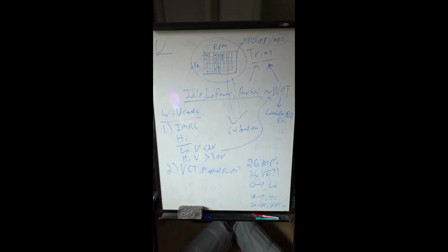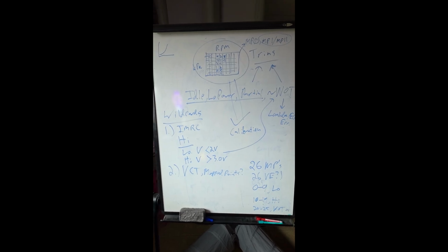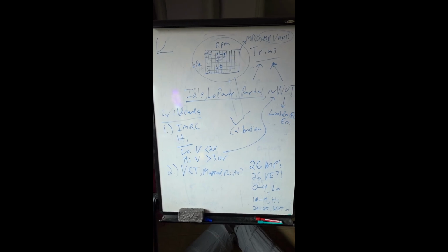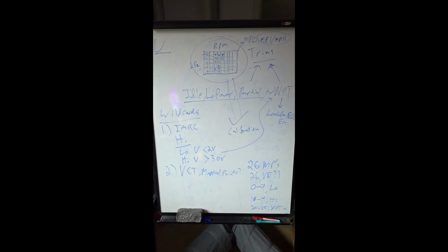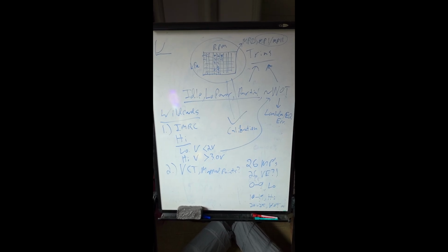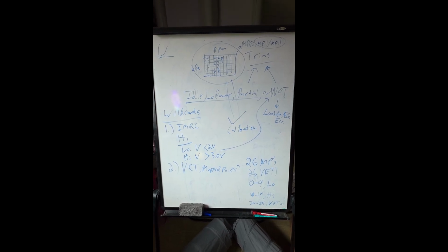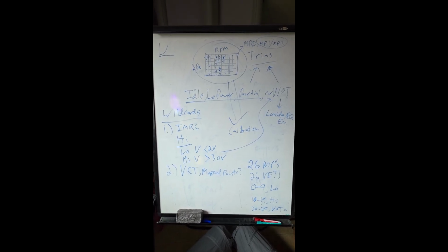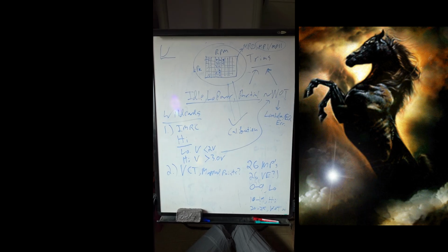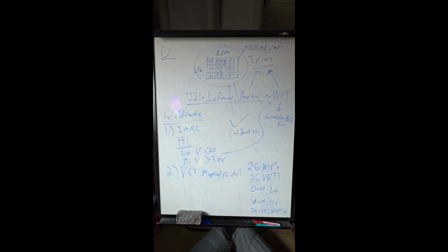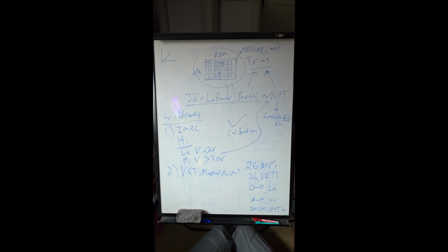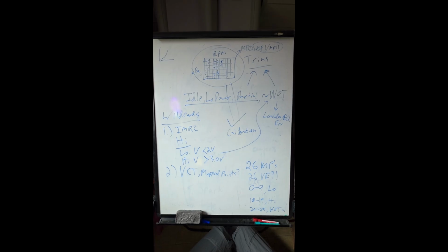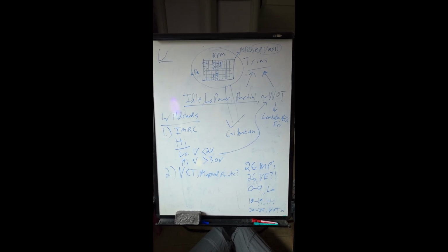So, we're not going to tackle all this in one video. There's too much going on. This is going to be video number 1. The next thing I'm going to show you are the filters I set up as I do logging. And then we're actually going to run a log on my car as it sits now, because I just layered in the Dark Horse torque limiters, which basically means by taking a GT tune file and adding in the Dark Horse torque control, along with a few other small goodies, you can essentially turn a Mustang GT into a Dark Horse.